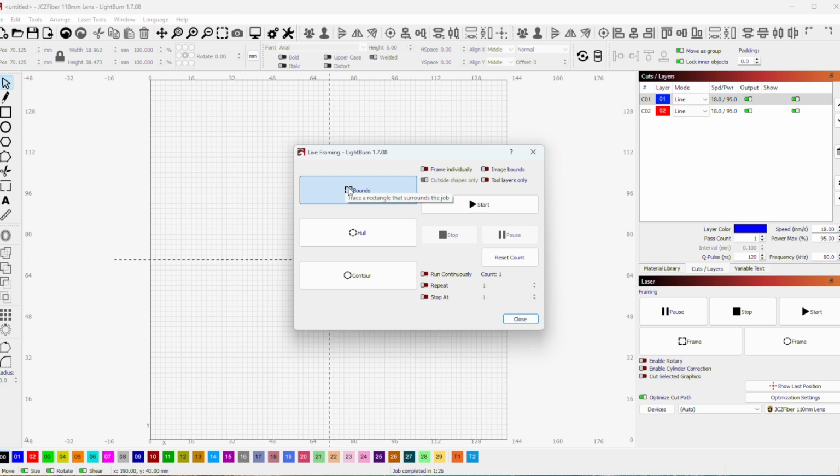The other thing too, when you're cutting these materials, especially in the jig we have here, is make sure it's flat as possible. It's very sensitive if there's a little bit of a kink or some curvature to your material in the vise, so make sure that it is as flat as possible. So take a look at it, make sure you're flat. Alrighty, well, we know we're in bounds, so what we're going to do now is we'll hit Start.